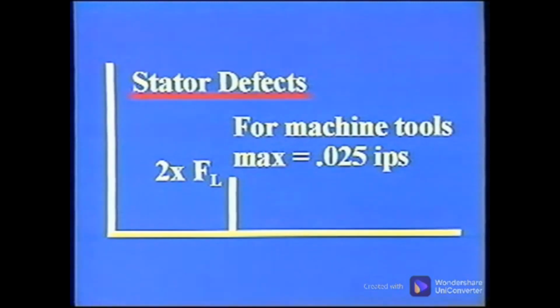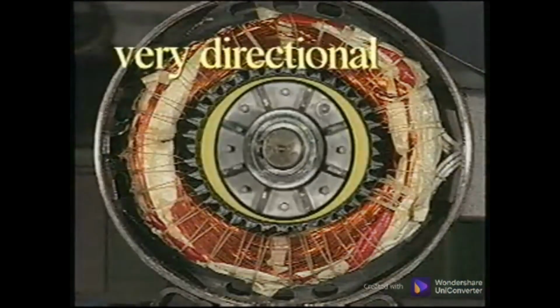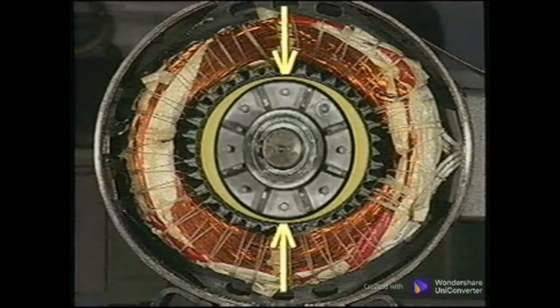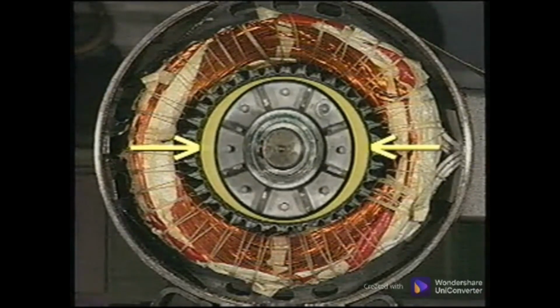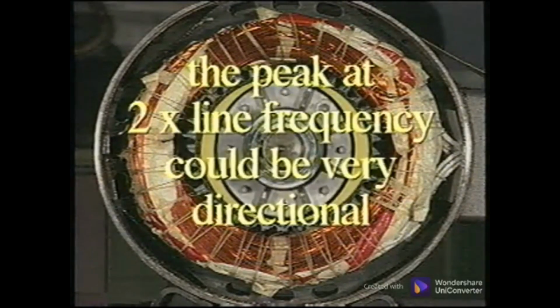If the motor is used in a machining process, the amplitude at 2 times line frequency should be less than 0.025 inches per second. In the case of eccentricity, the vibration may be very directional. In static eccentricity, the flux is strongest where the rotor and stator are closest, and weakest where they are the greatest distance apart. During one rotation, the rotor passes through the strongest field and the weakest field, causing pulsing and therefore high vibration. For this reason, the peak at 2 times line frequency could be very directional.